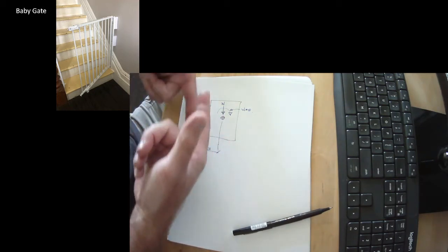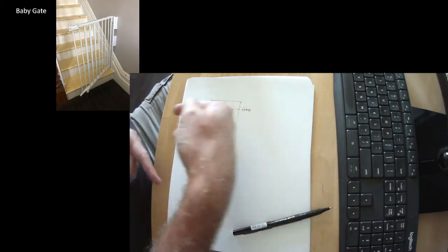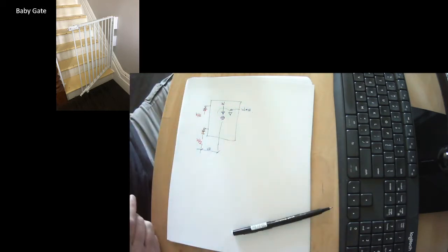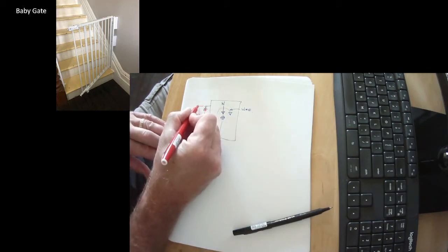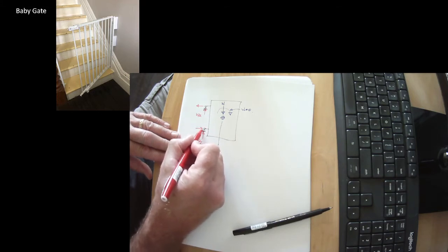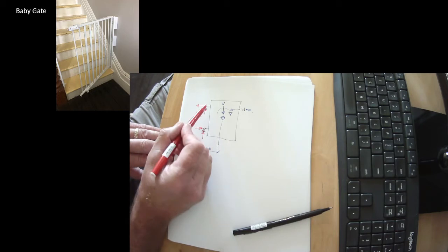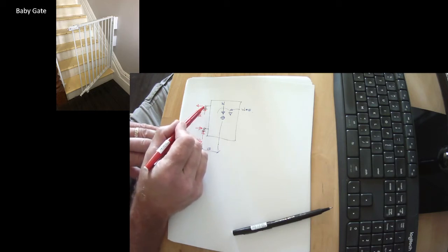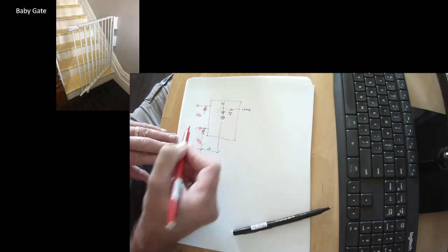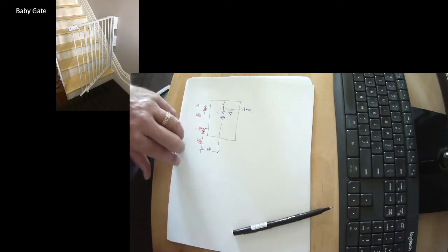We've got the vertical component taken care of. We have no external horizontal load on it. We could, but it's trivial. So what holds it in equilibrium? We need a couple on the hinges. So when you have a door, always the upper hinges are trying to pull out of the wall, where the bottom hinges are trying to push into the wall.